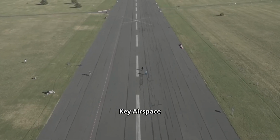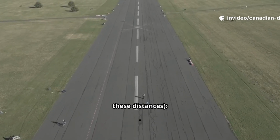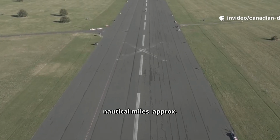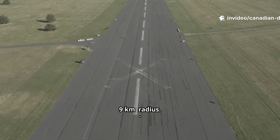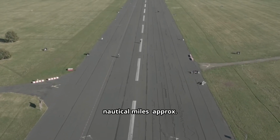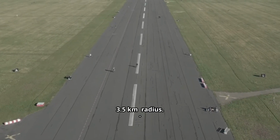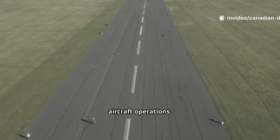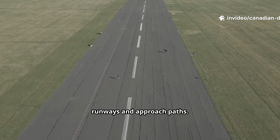D. Key airspace distances. Memorize these distances. Airports with a control tower: 5.6 nautical miles, approximately 9 kilometers, radius. Heliports with a control tower: 1.9 nautical miles, approximately 3.5 kilometers, radius. Aerodromes without a control tower: you must not interfere with aircraft operations. Keep well clear of runways and approach paths.